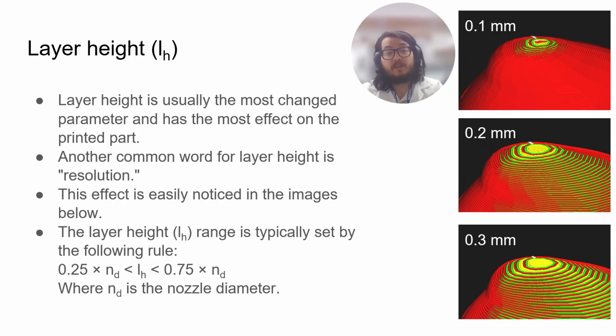You're just not gonna have good adhesion. What you want is some sort of adhesion and compaction to make sure that the different layers are sticking together. If it's too large, we actually have something called delamination or delayering, where the layer doesn't stick together very well with the others because, instead of having nicely pushed together layers, you're gonna have layers that are barely touching, and they're gonna have a very, very weak part where you can just snap it off.